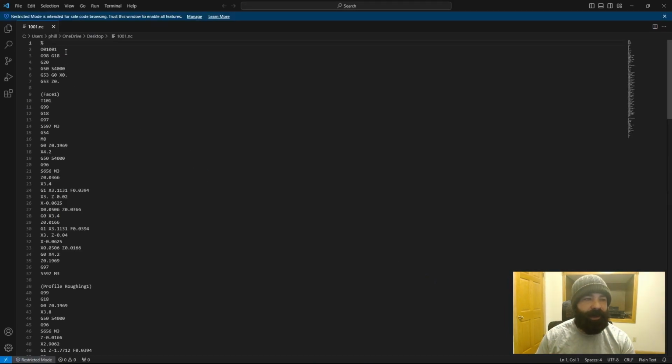As you can see, we are calling out our safe starts, our spindle speed clamps, our home position rapids, even our tool callouts, and then our spindle speed going into our cycle. Again, this is allowing me to offline program my parts, detect in the simulation whether or not I have collisions and problems, and get good known G code out of the machine.